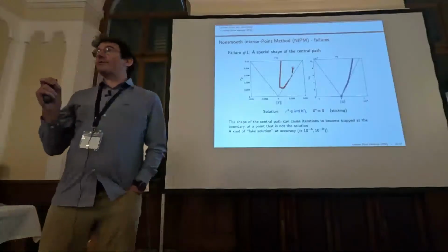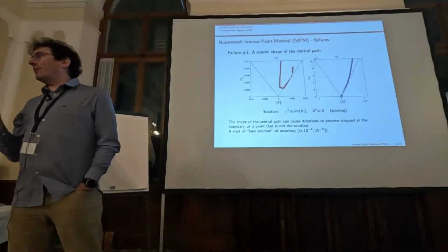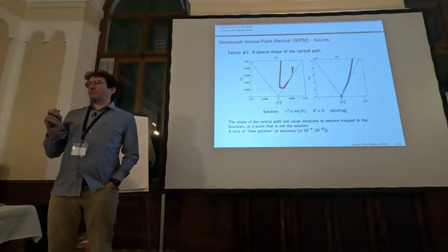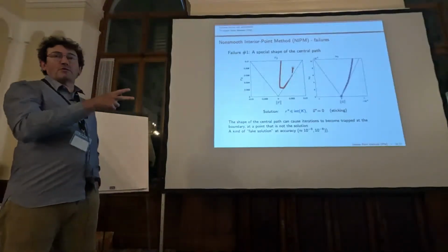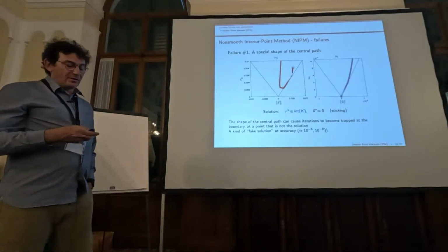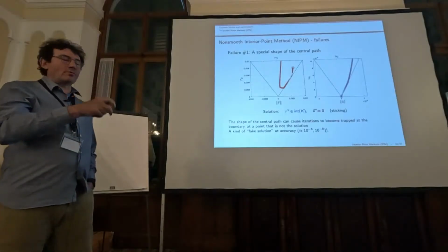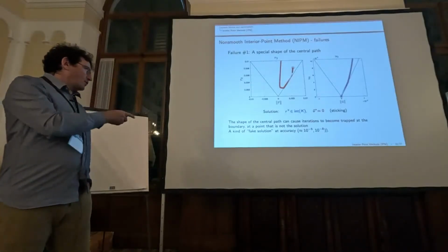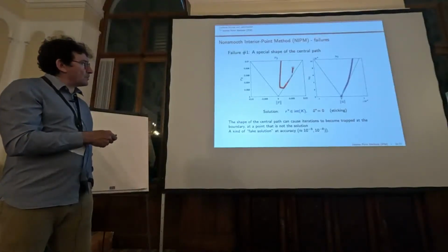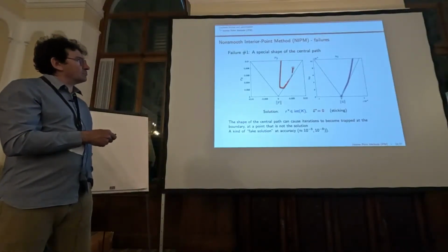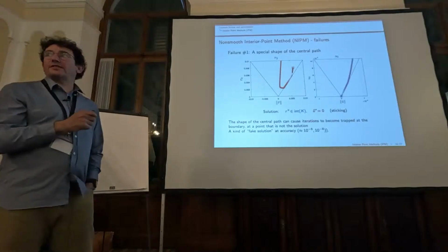Otherwise, you go out of your feasible domain, and then the algorithm stops. This is one of the problems that we get, and it is quite common, I want to say a generic problem. Most of the time the algorithm stops here, and we get some kind of fake solution. At least the contact status is not good.